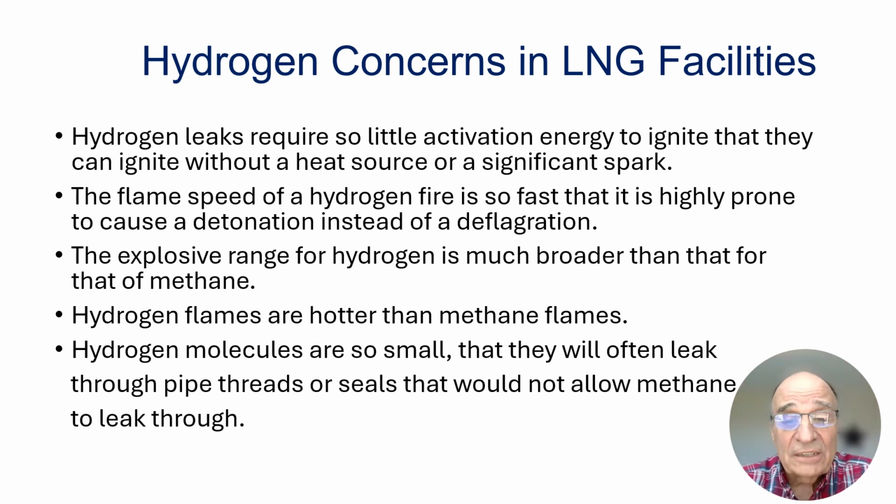The explosive range for hydrogen is much broader than natural gas. Natural gas is roughly 5 to 15% gas in air, and hydrogen is between 4 and 74% hydrogen in air. Hydrogen flames burn hotter than methane flames. A hydrogen molecule is so small that it'll often leak through leaks that would not occur if it was methane in the gas stream instead of hydrogen.